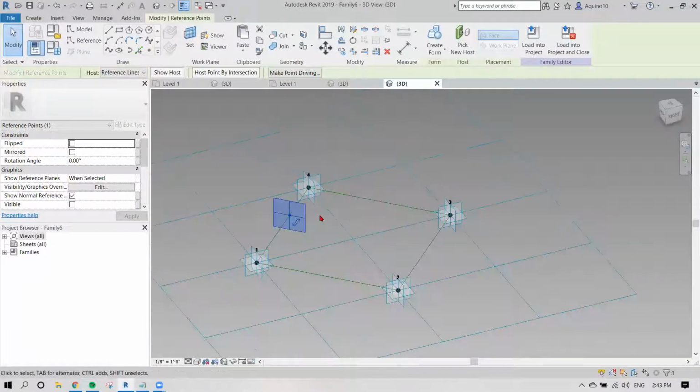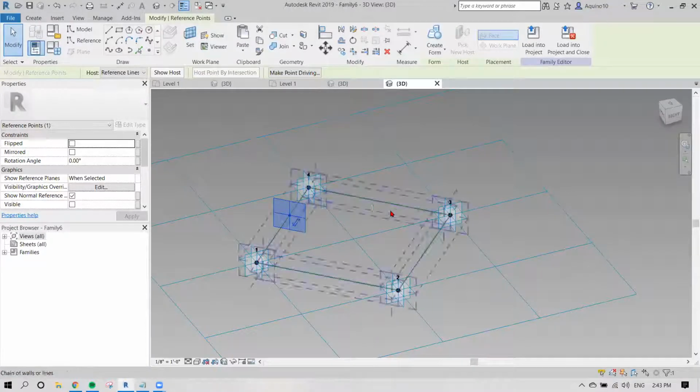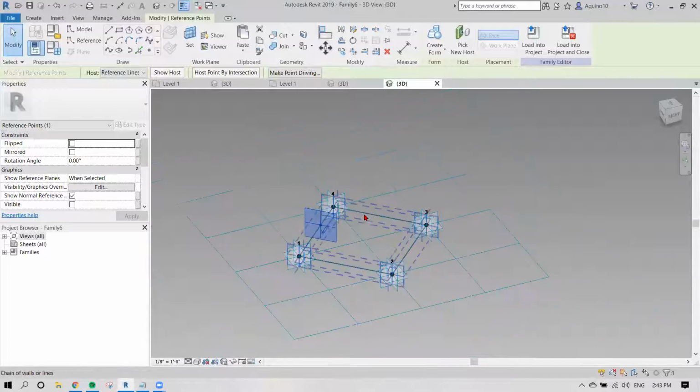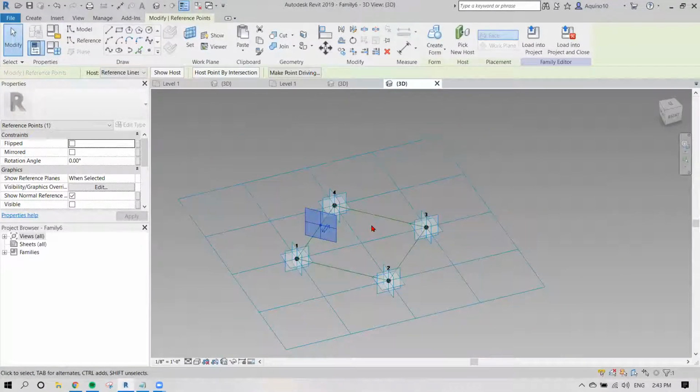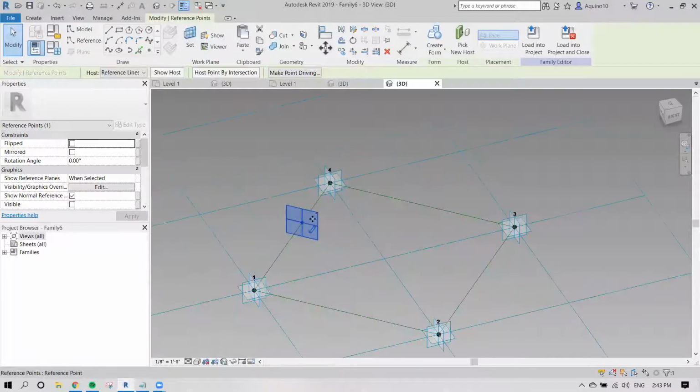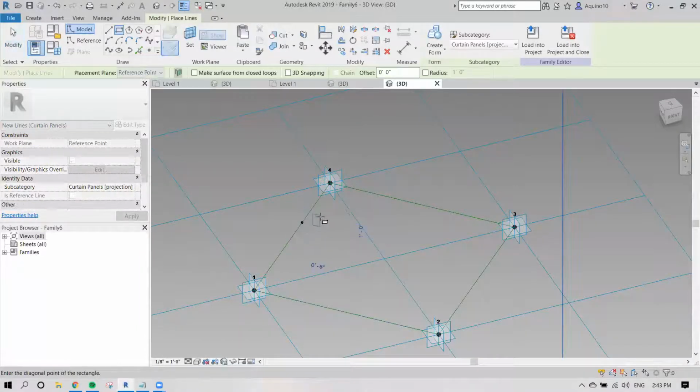Essentially what we want to do is extrude a profile along this rhomboid shape, or think of it like the sweep command in Rhino. So now that I have a work plane that is perpendicular, I can draw on it, and it'll be the profile that I desire.